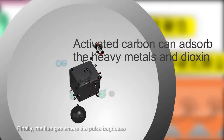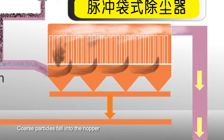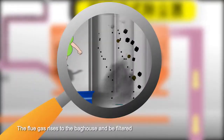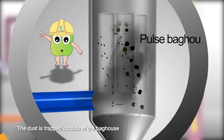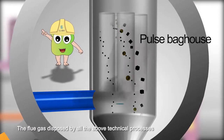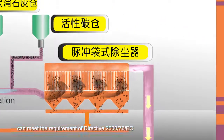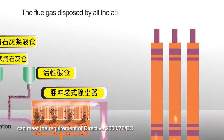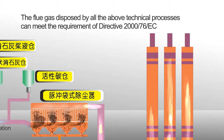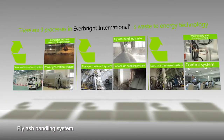Finally, flue gas enters the pulse baghouse. Coarse particles fall into the hopper, the flue gas rises to the baghouse and is filtered. The dust is trapped outside of the baghouse. The flue gas disposed by all the above technical processes can meet the requirement of Directive 2000/76/EC. 5. Fly ash handling system.